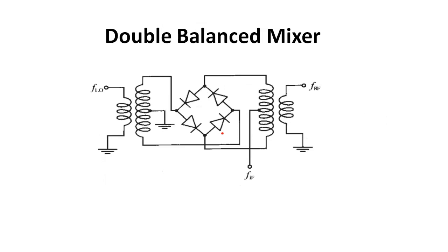Let us see double balanced mixer. The double balanced mixer can be constructed by using 4 diodes arranged in a rectifier configuration. The diode provides better isolation and an improved suppression of spurious modes. Unlike the single balanced approach, the double balanced design eliminates all even harmonics of both local oscillator and RF signals. In this double balanced design, all 3 signal paths are decoupled and the input and output transformers enable a symmetric mixing with the local oscillator signal.